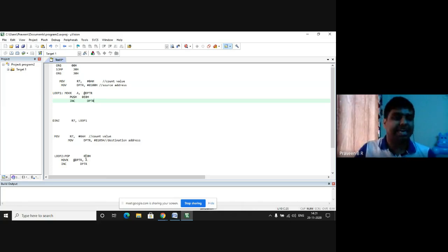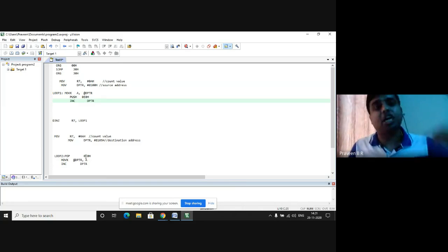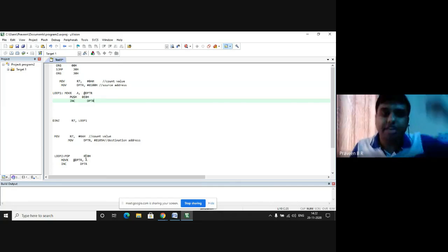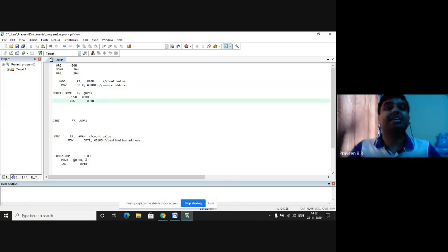So the last data that you have fed to the stack will pop out of the stack and go to the accumulator. Once it pops out of the stack, what happens? The stack gets decremented. In the case of the PUSH instruction, it had got incremented. In the case of the POP instruction, after the information is transferred to the accumulator, it gets decremented. What gets decremented?